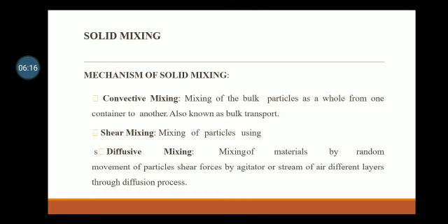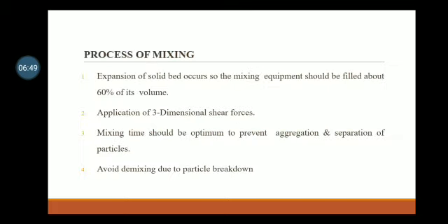Solid mixing: mechanism of solid mixing. Convective mixing: mixing of the bulk particles as a whole from one container to another, also known as bulk transport. Shear mixing: mixing of particles using shear forces by agitator or stream of air. Diffusive mixing: mixing of materials by random movement of particles in different layers through diffusion process.